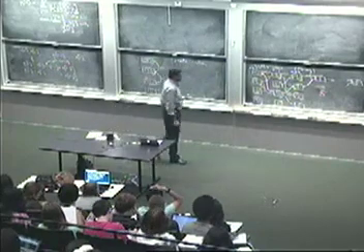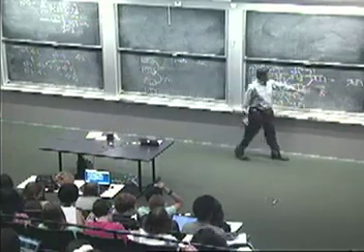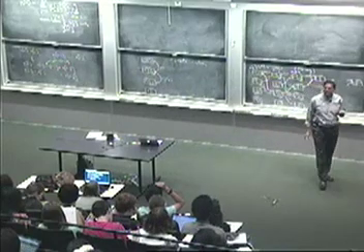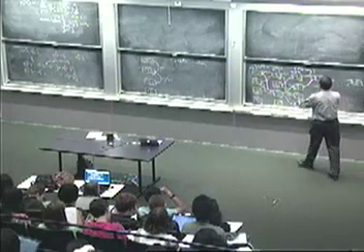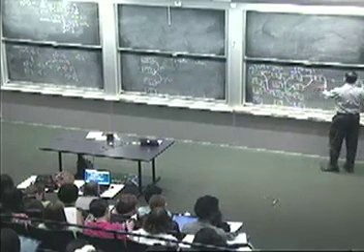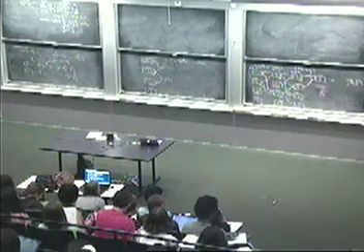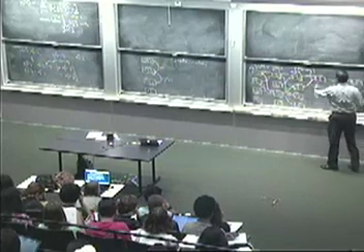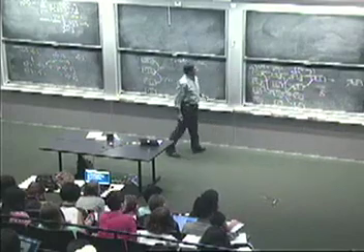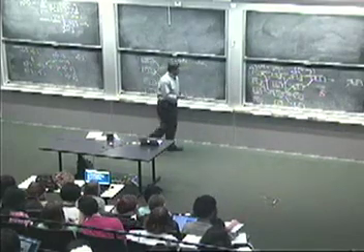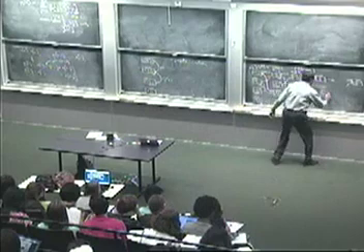Now, it turns out that the interpretation of this number is not quite as straightforward as the interpretation of minimum Hamming distance in block codes. And the reason is that this is a more complicated kind of picture because it continues on with the structure. So we don't actually call it the minimum Hamming distance, we call it the free distance.